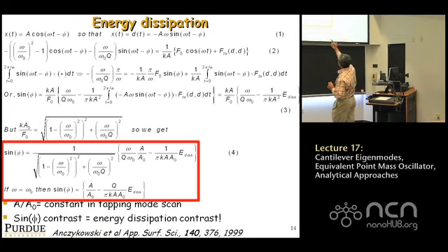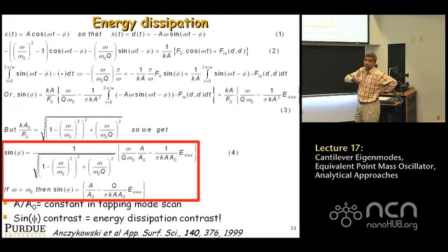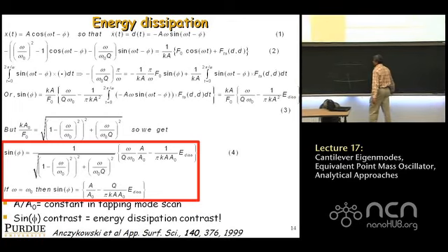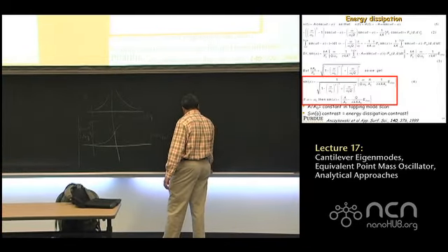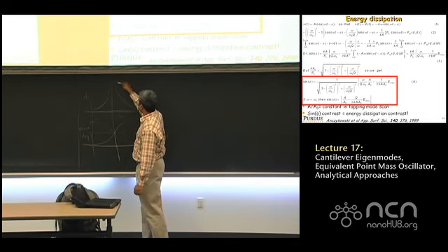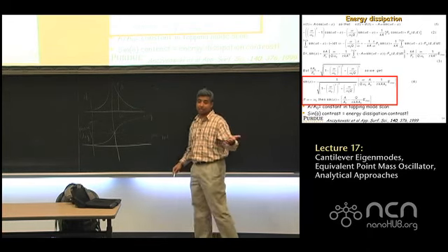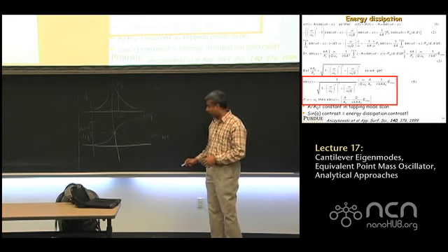So we're at equation 3. Now, we make use of a relationship that we had from before. What is the driving force F0? How do you know what the driving force F0 is? Well, you've done a tuning curve, right? So you know the tuning curve, and when you're far from a sample, you've chosen to drive it at resonance with an initial amplitude A0. A0 is the initial amplitude, or sometimes people call it free amplitude.